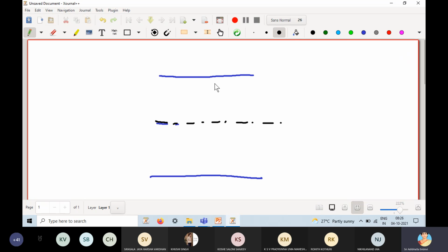After that, they have PMOS in series and NMOS in parallel. So they draw the PMOS stick like this, and the NMOS in parallel, the NMOS stick like this. And they provide electrical contact here, here and here. But here it's a 2-input NOR gate, so we have 2 P diffusions. So I'm drawing 2 PMOS like this, and here also like this.